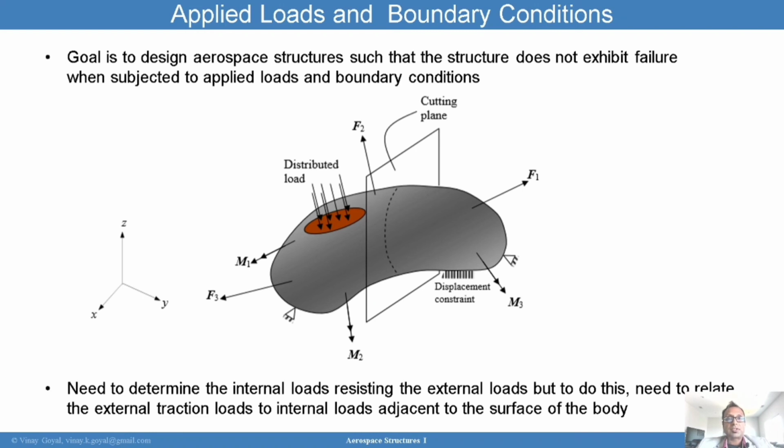An airplane that's flying in the air does not have physical boundary conditions that are fixing the airplane in the air. But yet the airplane is flying and is in equilibrium because the forces applied to the structure are getting balanced correctly by the inertial loads of the structure.